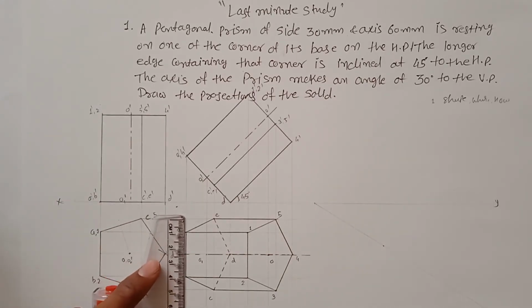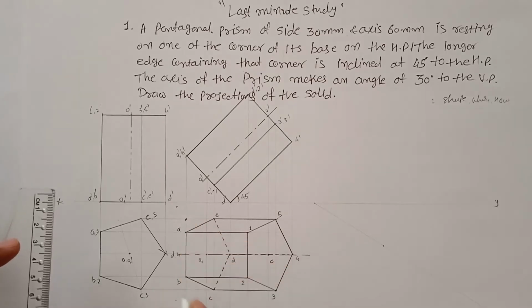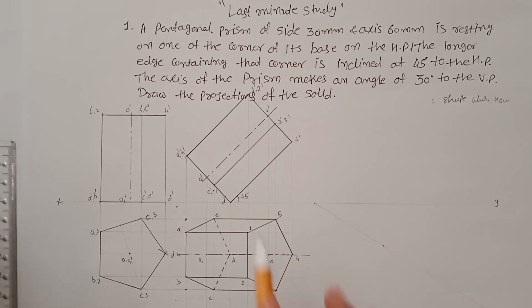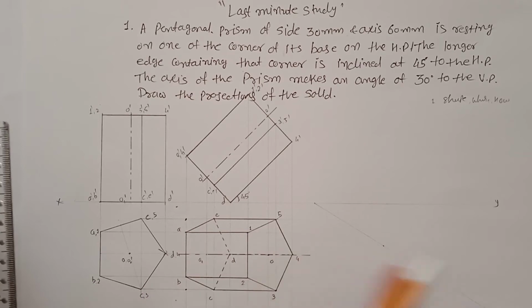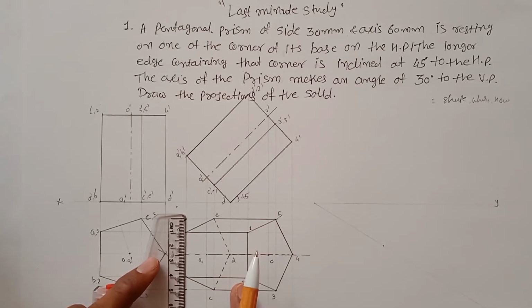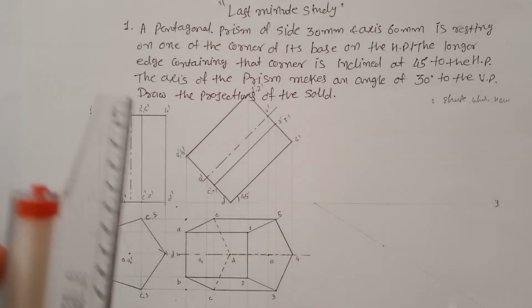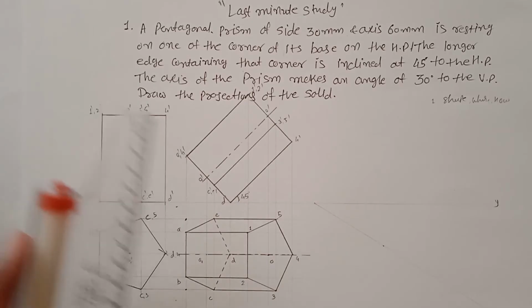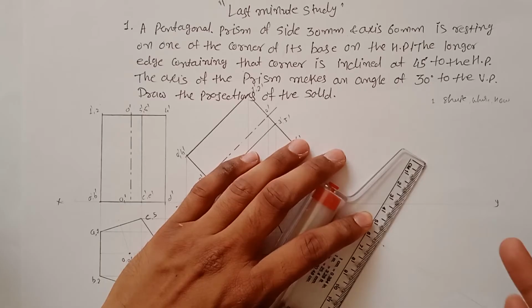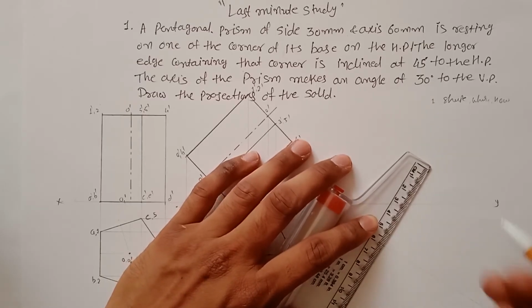So first of all, measure these corners. I am talking about these corners, this line, because we are going to construct the whole rectangle here, and then the inside structure of the lines, and then we are going to find out the intersecting points of this solid and complete our structure. So this distance, from this point to this point, is around 4.8. So you have to draw a line at 4.8 distance. So 4.8 means 2.4 from both sides.